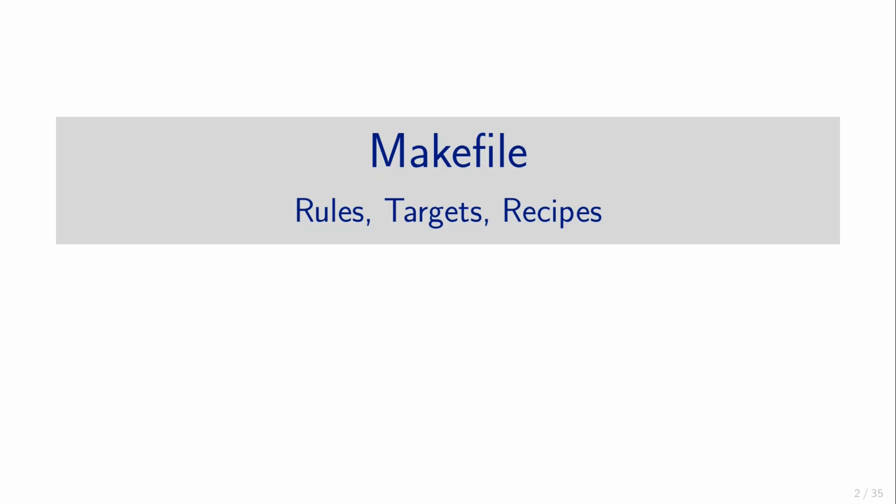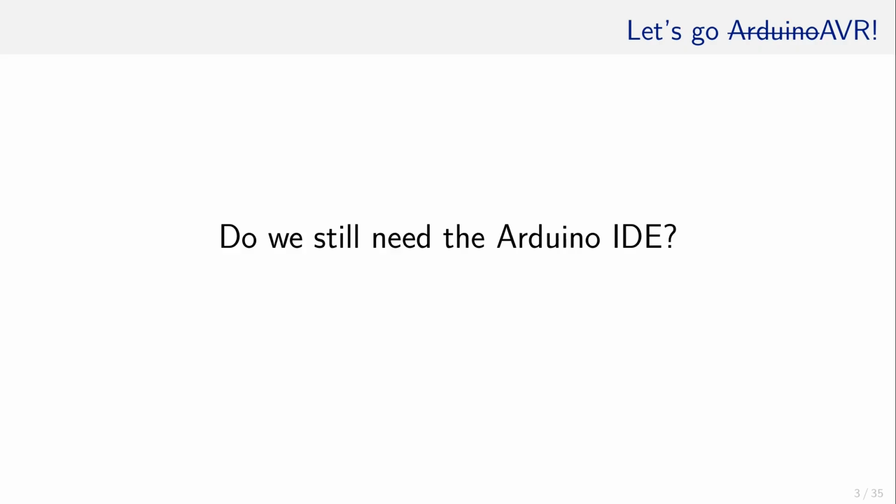That is not related to programming or C, but to support the compilation process, the Makefile. In the last chapter, we asked an important question. If we do not use function calls such as digital write, pin mode, and so on that are supplied by the Arduino library, why do we still have to use the Arduino IDE? That is a very valid question, and although we do not use those function calls anymore, at the moment we still need it to compile and upload our programs. However, in this lecture, we will write programs without Arduino support, but solely depending on the AVR library.